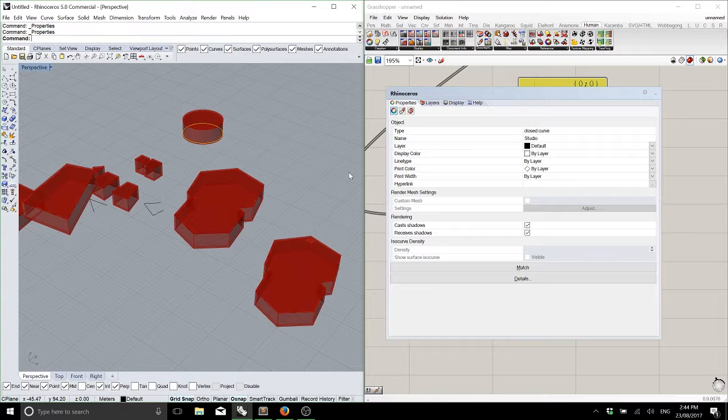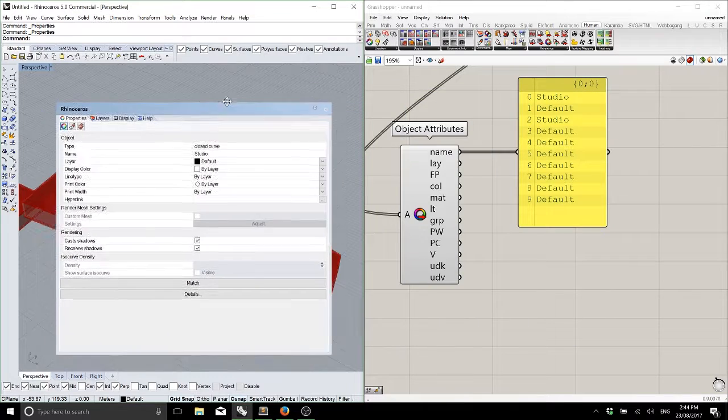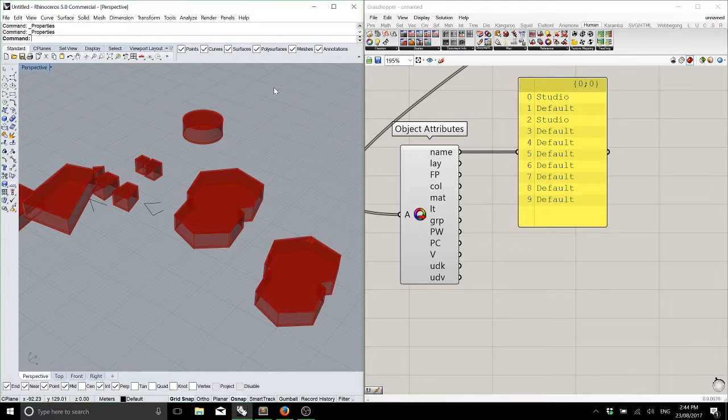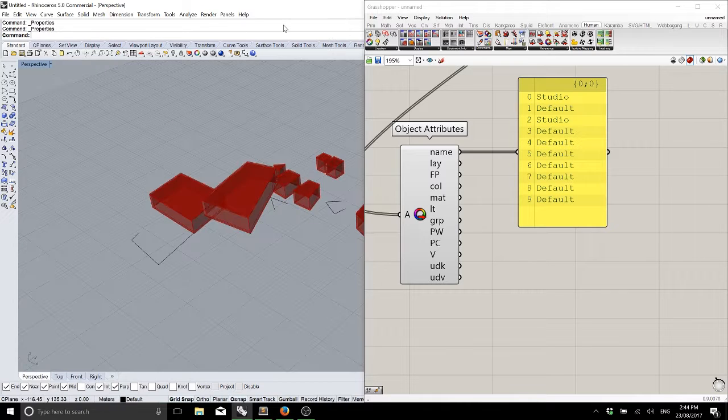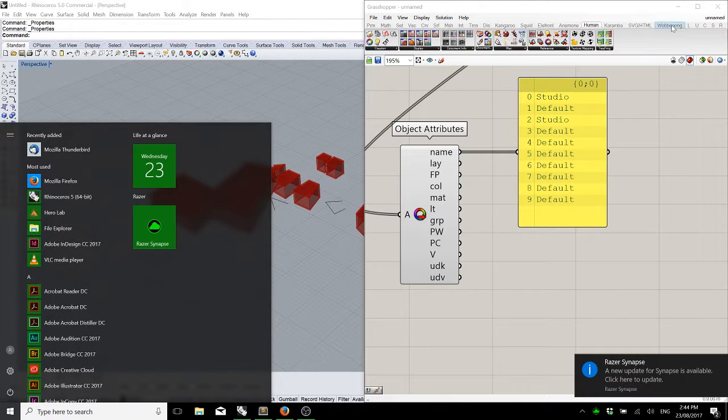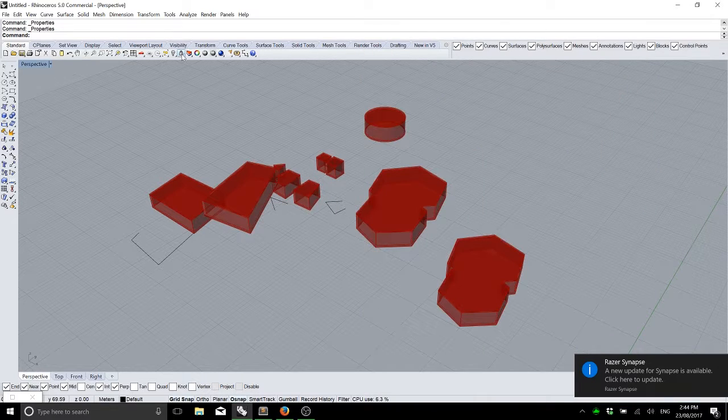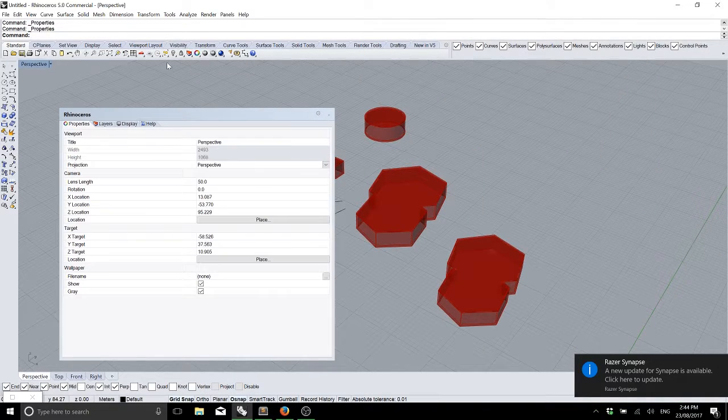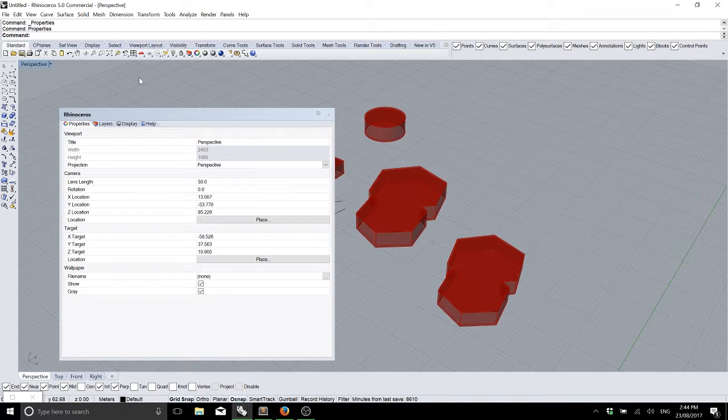It's in Rhino. We're assigning these properties to Rhino objects. Can you please get that property box up again? Okay, if I maximize Rhino, we can find it under this rainbow wheel here, or you can type properties into the command bar and it will show you the properties panel. Or if you've already got layers up, it should be a tab next to layers.